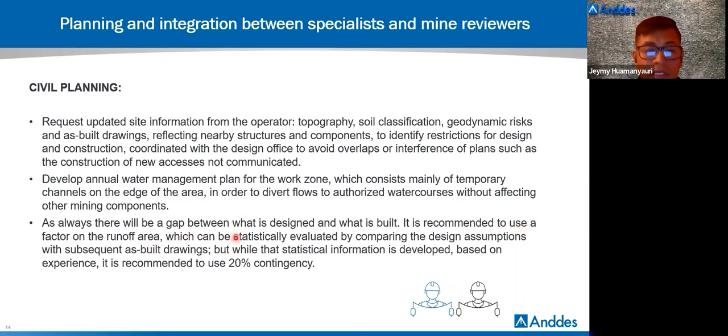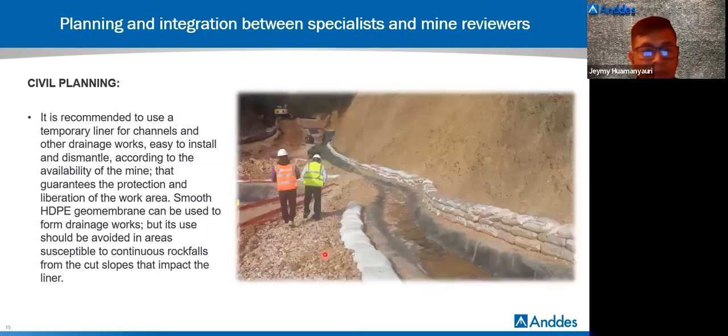Consider that the design is different from what is built. For this reason, maintain 20% of contingencies of capex. It's recommended to use temporary liner for channels and hydraulic structures, like HDPE geomembrane, which is easy to use and easy to retire.